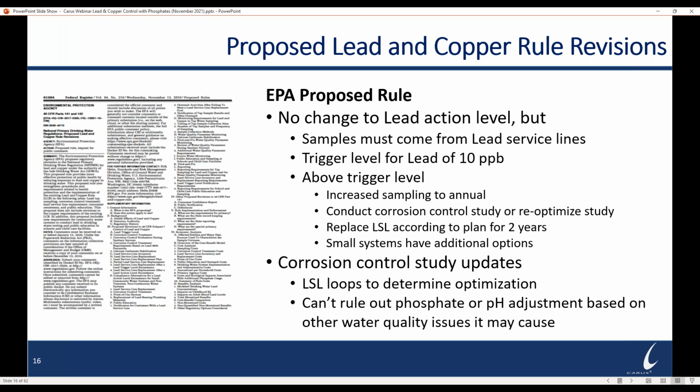The other part of the lead sampling is you're going to have a first draw and a 5th liter draw sample. So there'll be 2 samples that you pull for lead compliance, whereas the copper will still stay as only the first draw sample.